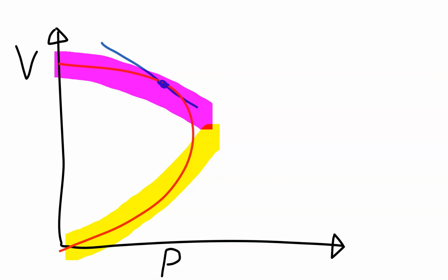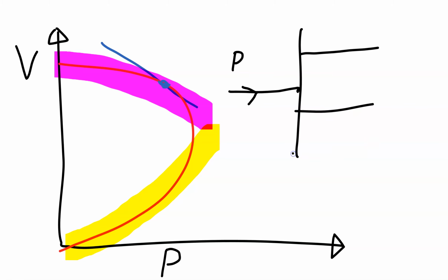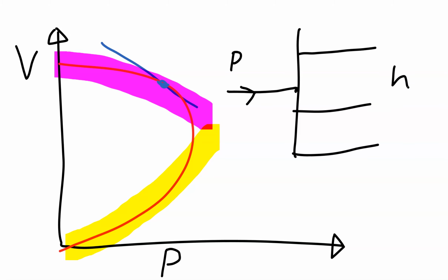Another important issue for doing this load flow is the n-1 evaluation. If we call this a bus bar, and you have a flow of power coming into this grid, and then let's say we have 3 lines going out from the same connection point, so n is equal to 3, we call it the n-1 criteria.